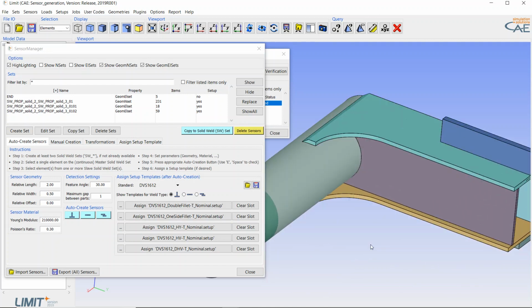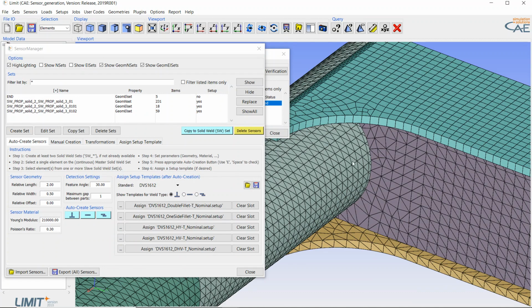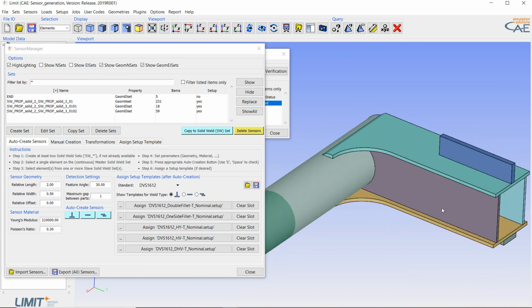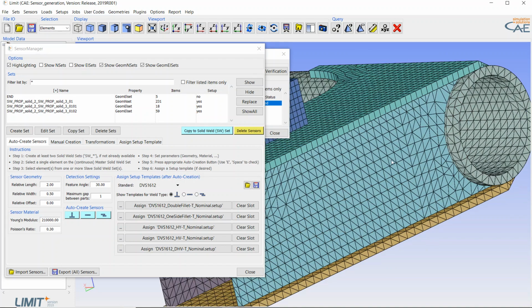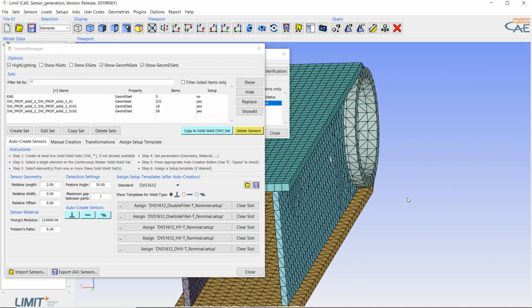on the surface, this usually means that you missed a surface element and some other element in the background was highlighted. So the only way to fix this is to hit the escape button and to delete the complete selection buffer and to start from the beginning, and maybe even show the element edges so you have a better vision of the surfaces.